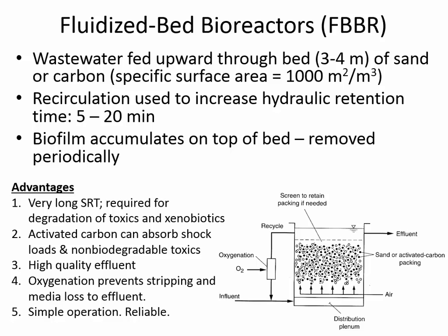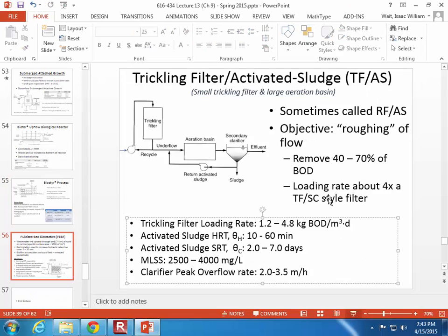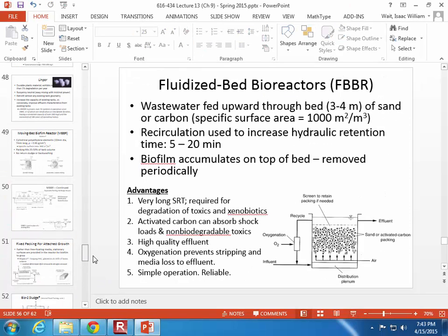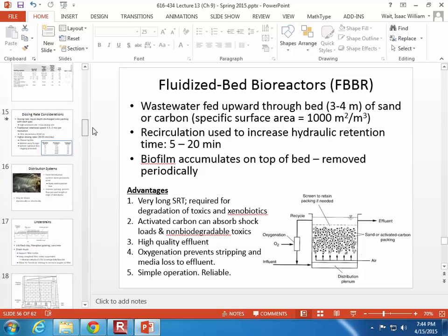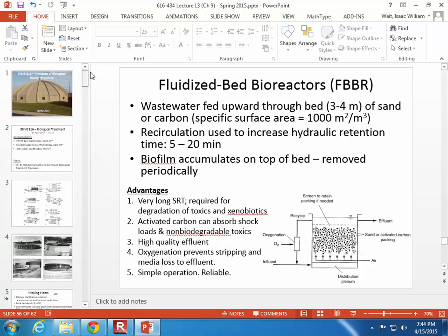The biofilm is growing on the surface, and then it sloughs off when it gets too thick, and then it just floats to the surface and stays at the top, and then they would screen it off in the same way that we saw that moving conveyor belt at the top of the clarifiers at the treatment plant in Huntington, by sweeping off the solids that float to the top of the surface there. Then it's just kind of a simpler way of removing the slime layer that sloughs off. So those give you kind of an idea of the exotic directions that attached growth has gone.